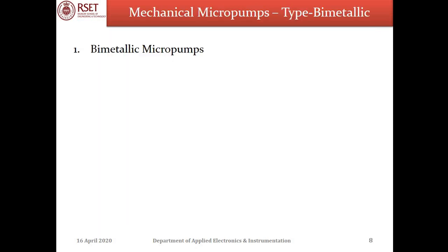Well, we have already discussed electrostatic micropumps, which use electrostatic forces in their actuation mechanism. That is, the pressure difference induced by the membrane deflection in the pump chamber forces fluid in the reservoir to flow in the microchannels. So that was regarding electrostatic micropumps. Then we also dealt with the piezoelectric micropumps, which are based on the principle of piezoelectric actuation.